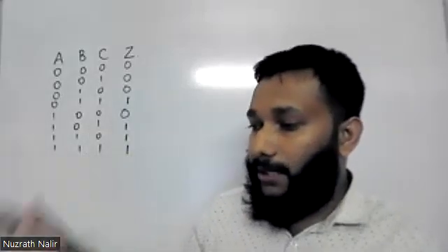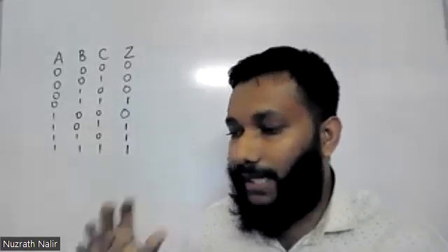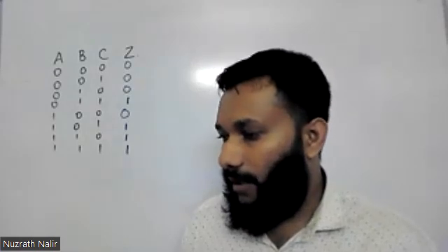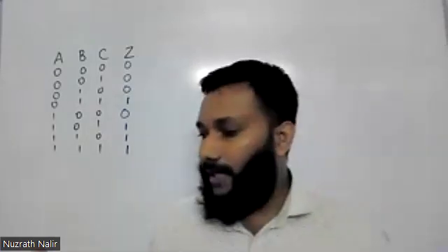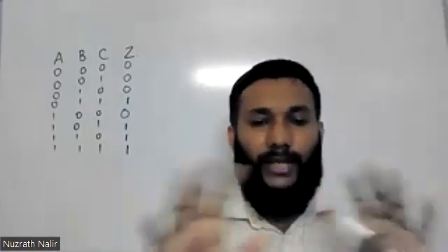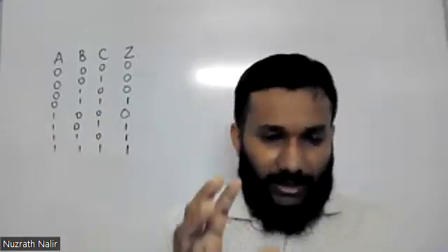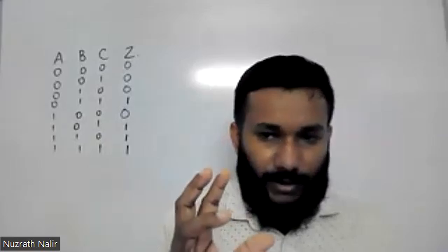And the B part says: using a K-Map, Karnaugh Map, derive a simplified Boolean expression for the output Z of the 3 input majority function. When the Karnaugh Map is mentioned without any other SOP or POS, typically we use SOP. Clear?